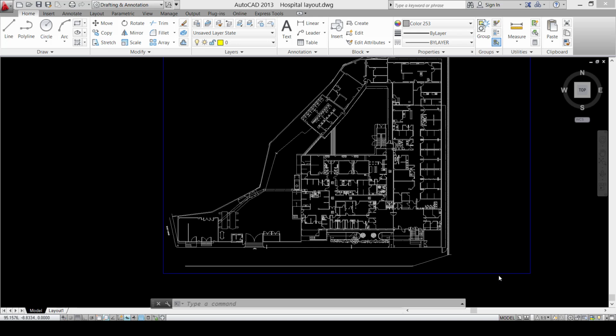In the previous tutorial, we finished the handling process of the hospital layout as a pre-design step for the design to be ready for the lighting design. Now the first step we need to perform is to insert the luminaires we have designed before. If you remember, we designed the lighting system for some rooms of this hospital in the DIALux software, so we now need to export those lighting systems from the DIALux design to the CAD design.